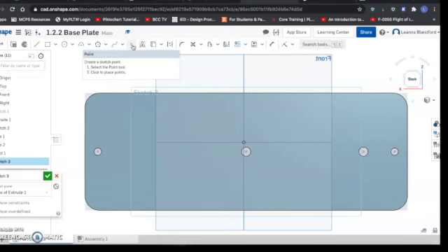So if we look, those holes are located in the 4 corners, and they are located about, I'm going to say, probably about 1/4 of an inch in, looking at that blueprint. We don't actually have a measurement, but we're going to work on it. If we look at the blueprint, it actually has us centering them right there where that point pops up. And that is the center mark for the fillets that we created. So we're going to use that as a guide to place those points. And I'm going to finish my sketch.